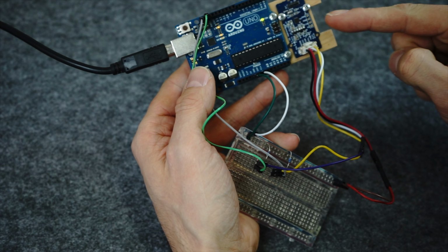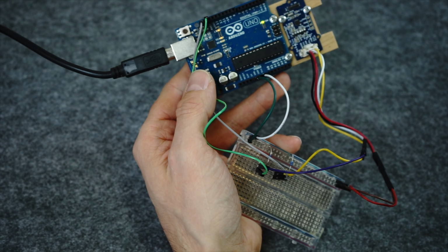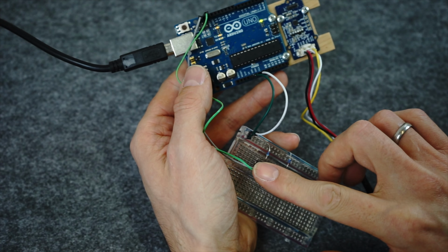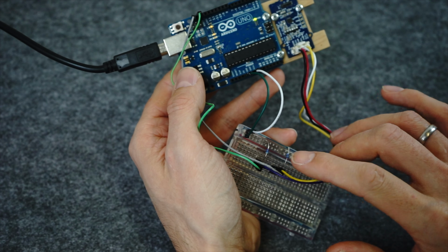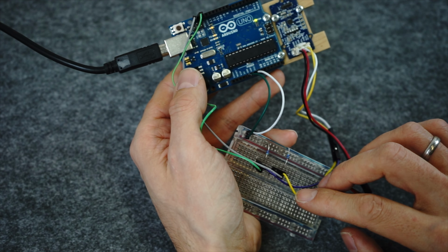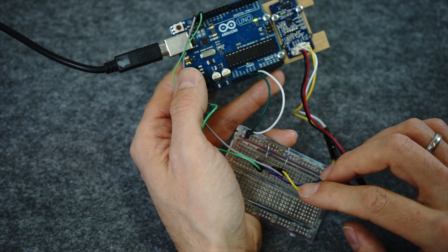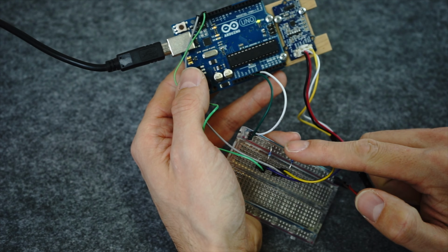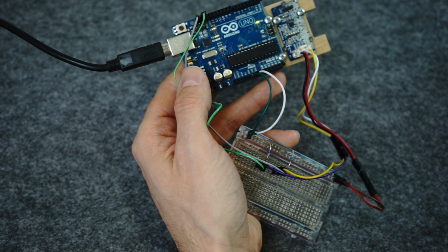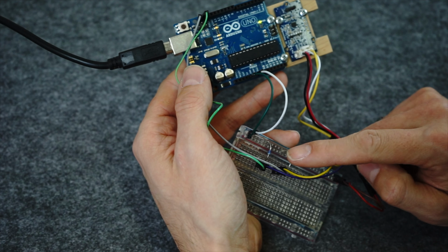The I2C lines, SDA and SCL, are directly connected to the IMU. You may then stumble across these 2 resistors here. These are the pull-up resistors we talked about earlier. I selected 4.7 kiloohms here. So if something is wrong or just not actually as you expected, first take a closer look at your setup and see if you haven't forgotten these pull-ups here.